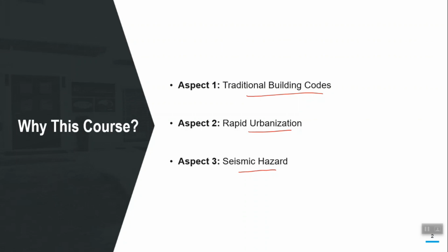Actually, this performance based approach is more general. It is primarily developed for seismic analysis and design, but this methodology itself can be applied to any other loads also. For example, currently there are a lot of efforts to extend this methodology to wind loading. If you just search for performance based wind design, you will find many reference documents and even standards which discuss the extension of this approach to wind loading also.